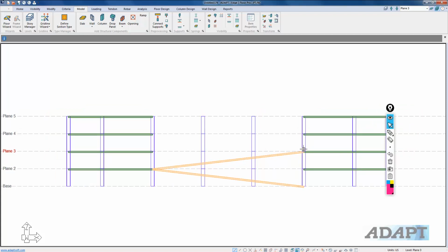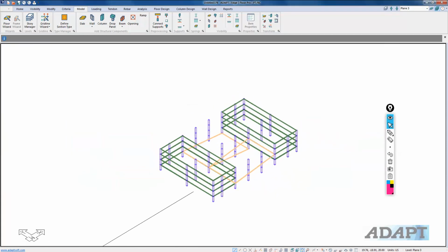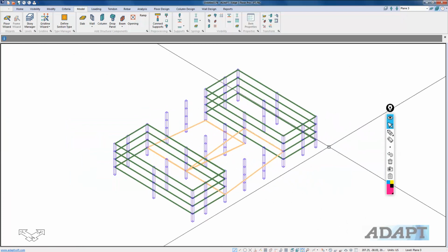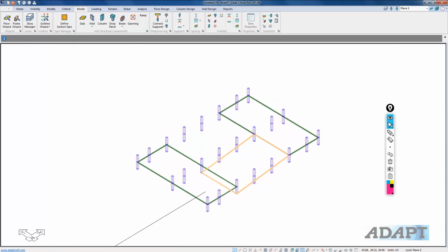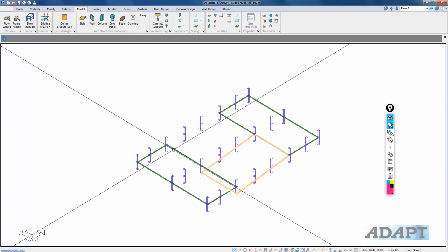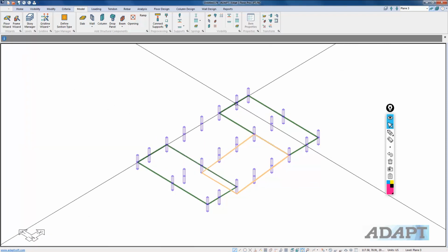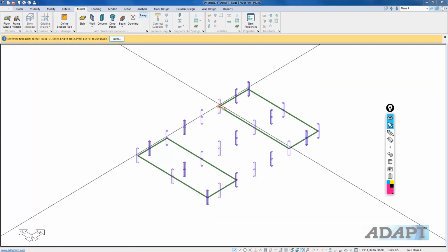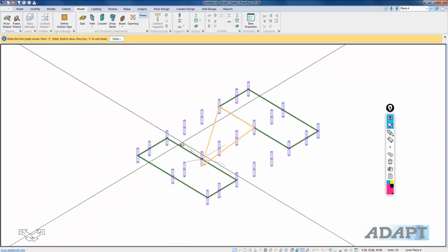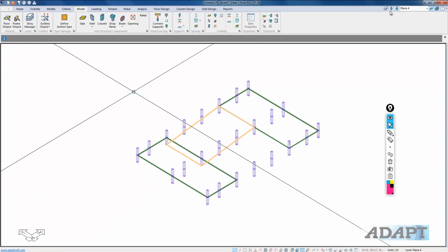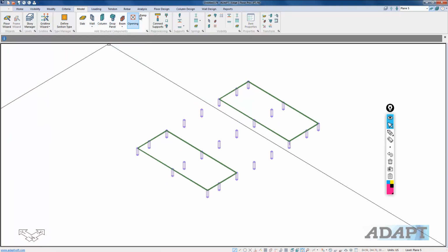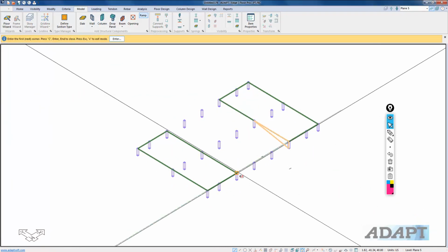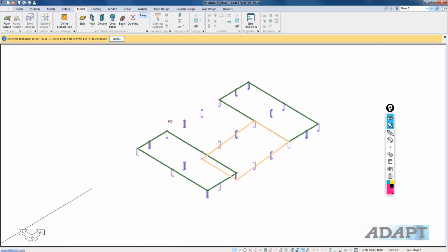This is on the near bay here, going from level 3 to 4, and this is the view like so. If I wanted to repeat this pattern, for example, now we want to go to level 4, and this will go from this point up to level 4. So I want to go up to level 4, and I'm going to define this ramp from here, let's say down to here. I'll go up to level 5, and I'll define, for example, this ramp from there down to there.